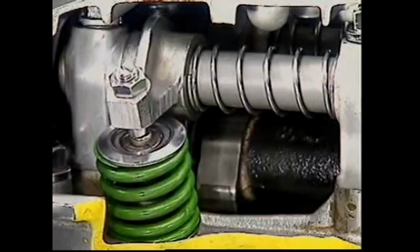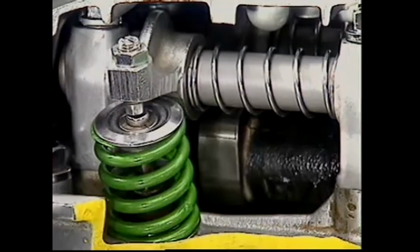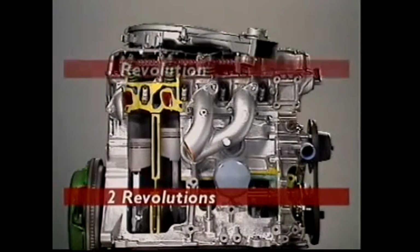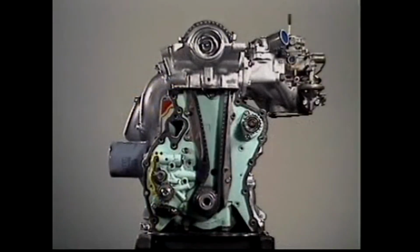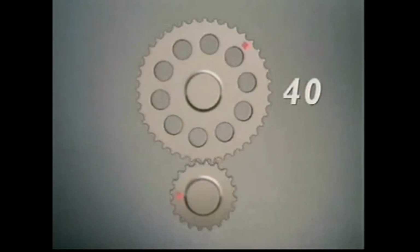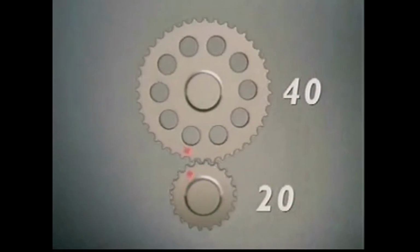So the cams must turn through just 1 revolution, as does the camshaft. In each cycle, the crankshaft turns twice and the camshaft only once, so the camshaft must turn at half the speed of the crankshaft. One way to do this is with gears. One of these gears has 40 teeth and the other, the driving gear, has 20. When they mesh, the larger one rotates at half the speed of the smaller.